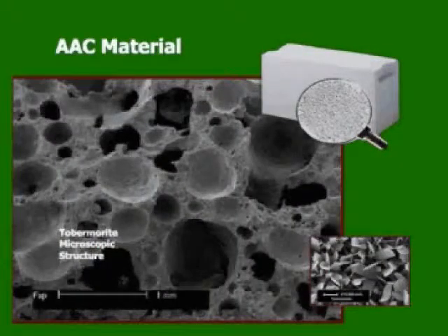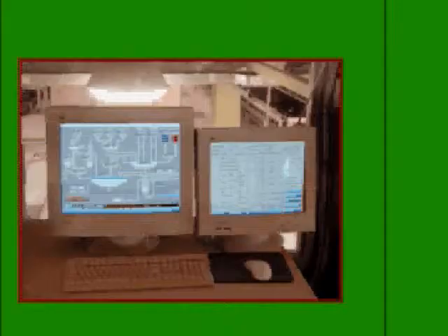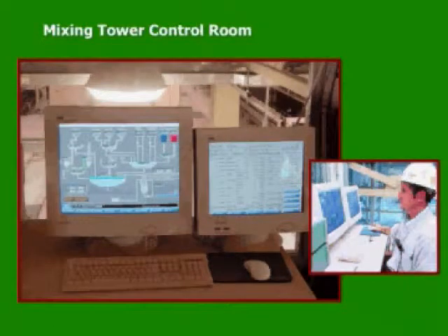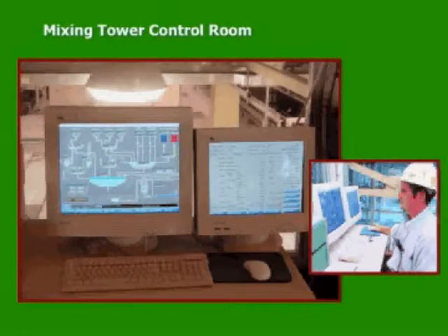The final hydration product is also called tobermorite, as seen here under a microscope. You can see numerous air pockets, however not all are connected, which gives AAC its unique properties. Most AAC facilities are well advanced and have just a few workers. Everything is computerized and robots are pouring, moving and autoclaving the product. The technology today makes it possible that each mixture ratio is very accurate, controlled by computers, and the material has just 1/32 of an inch size differential.